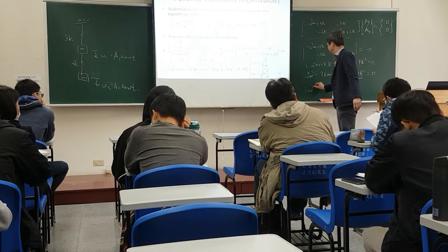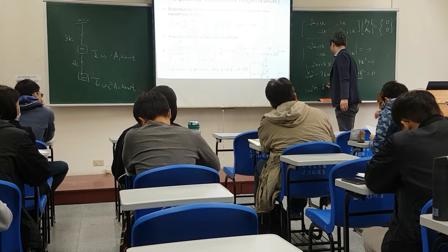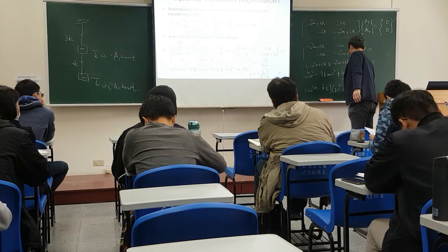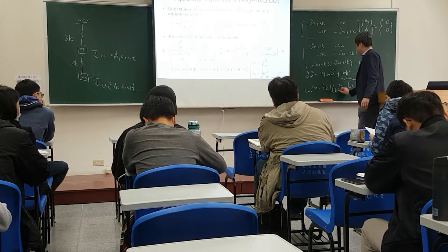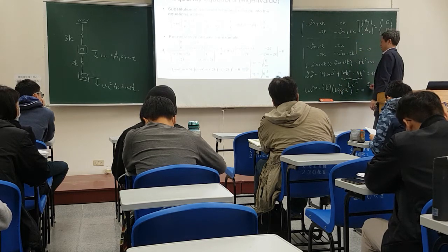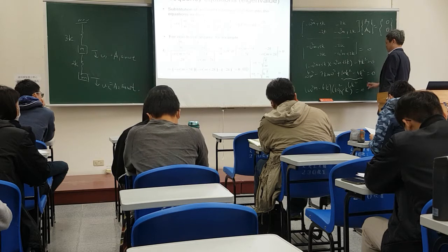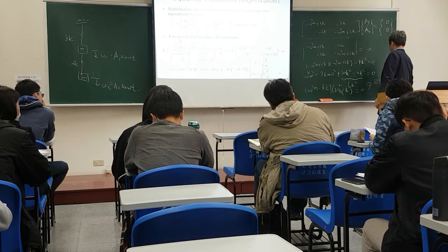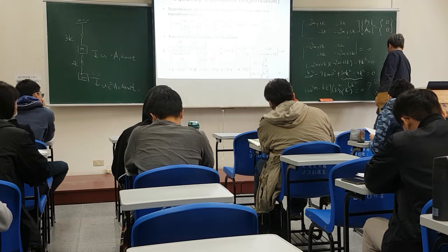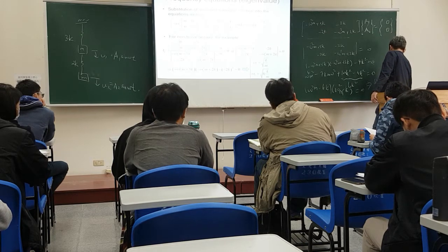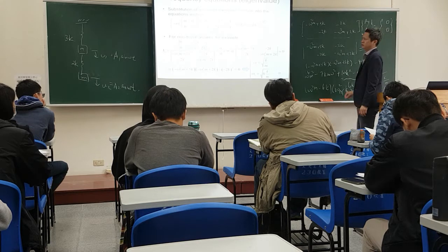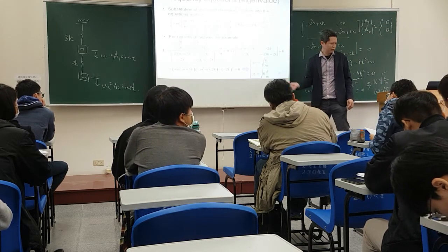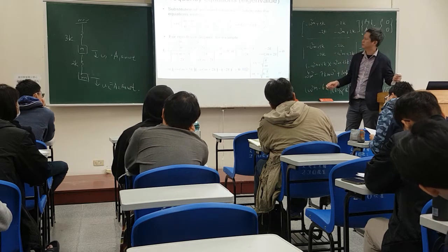Whichever way you use, you know the solution should be like this. So your omega has two solutions: the first is the square root of k over m, and the second is the square root of 6k over m. So this is how you find your natural frequency. But next thing I'm going to ask you is, will you be able to find the mode shape?